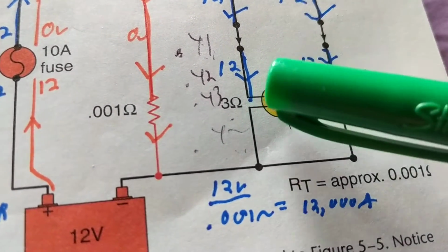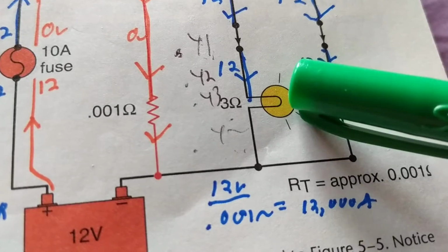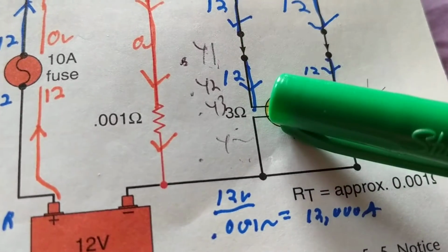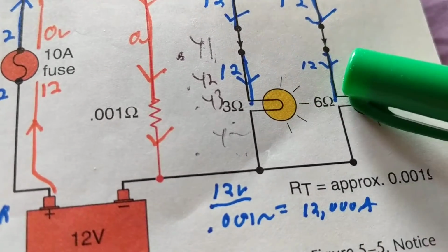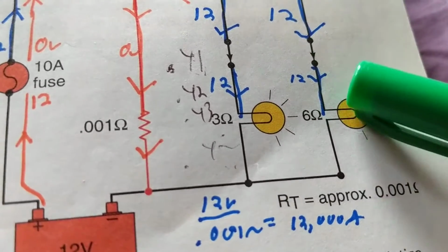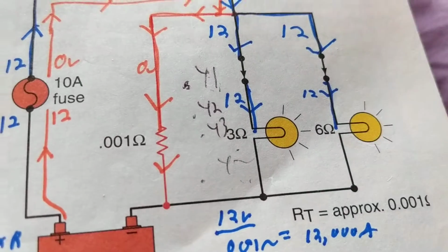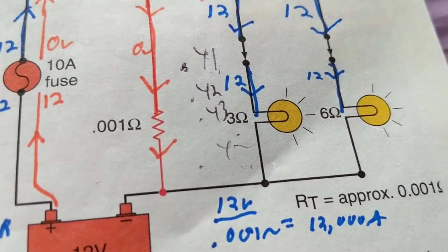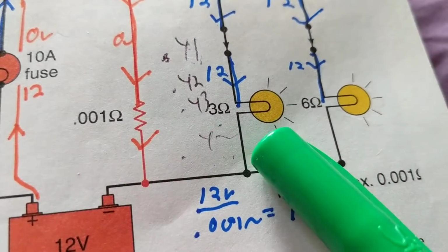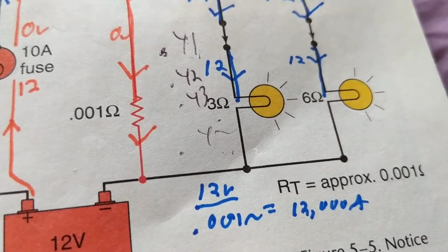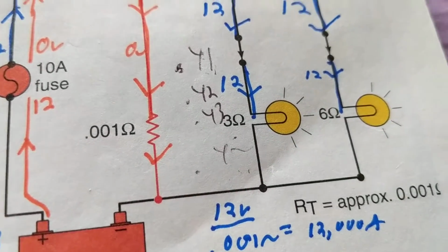Okay? Again, the headlamps. Left is good, right is not good. Okay, I know I'm dealing, obviously, with something with this one. It has nothing to do with a fuse because the fuse will blow both. Right? It has nothing to do with a bad ground because if it was a bad ground, both of them would be out. It's a common point right here.